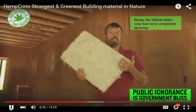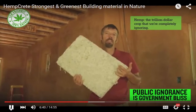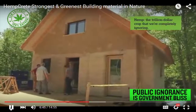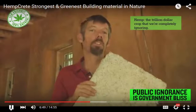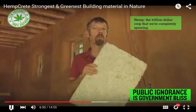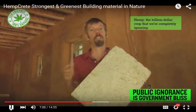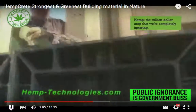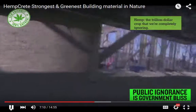So the Hempcrete in this building, this one building alone, will sequester 20,000 pounds of carbon. That's a pretty big accomplishment, and it's all thanks to Hempcrete. Hempcrete is part of the natural building world. What are natural materials? They're basically materials that are usually local or site harvested or have low embodied energy like Hempcrete does. They're also materials that work well with the site, and one thing that's great about Hempcrete is that you can create a strong wall of different thicknesses based on what your insulation needs are. That's because you use forms around some kind of other structure like wood that will hold up the roof, and then you form around that and put the Hempcrete in the cavity.